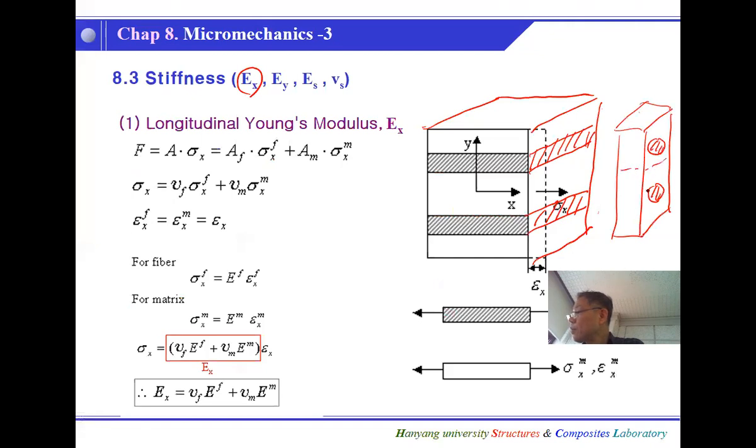So in this one and that one, this fiber and resin arrangement is assumed to be just layered between the resin matrix and fiber, and matrix and fiber. This is the simplest model of the fiber within a ply. And then by definition of this Young's modulus EX, the extensional properties, we first need to define the total force